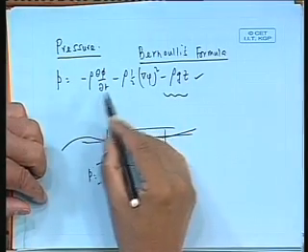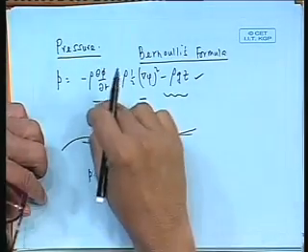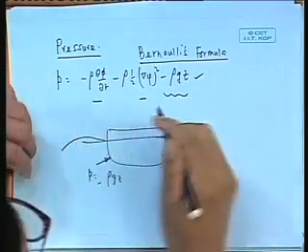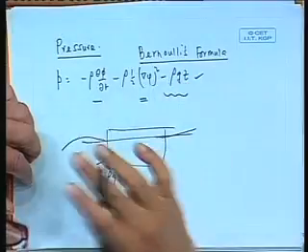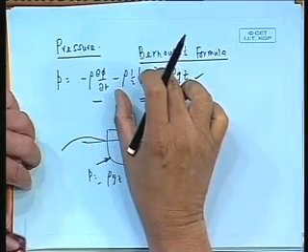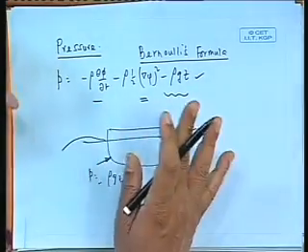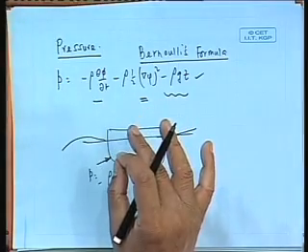Now Bernoulli's equation tells me there are two parts, one is this part, one is this part. This part is called the linear dynamic pressure, because this is the main pressure. This other part is a pressure coming because of the square of the velocity. We will neglect that for the time being, because it turns out to be much smaller compared to this part. So pressure can be written as minus rho d phi by dt. That means it is a time derivative of phi. Everything comes again to phi. So look at the phi formula, and then we can go to the pressure.